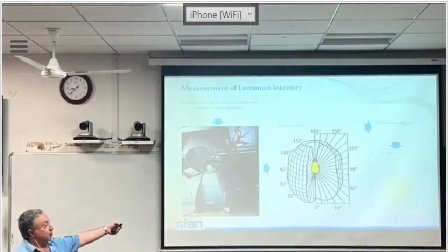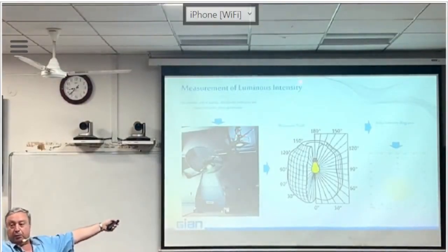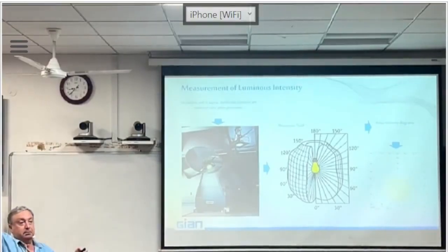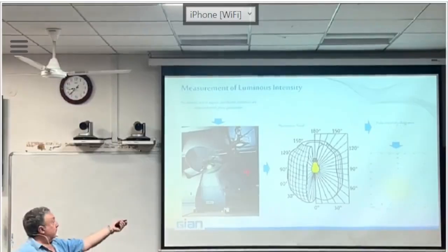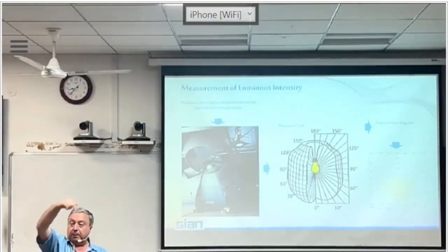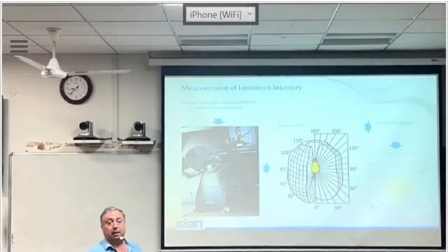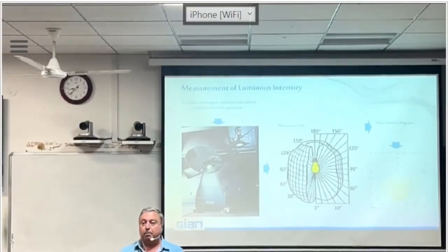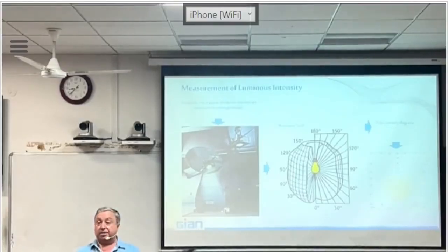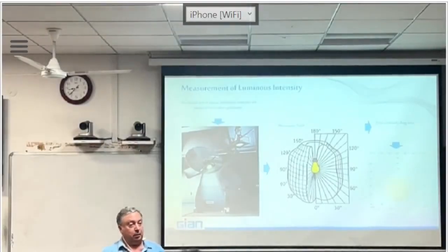That means the moving part is a mirror 3 meters further away that sends the light to a calibrated radiometer, and you can scan the system. All the system has to be in a black room without parasitic light, with stabilized temperature plus or minus 0.1 degree, with stabilized humidity.